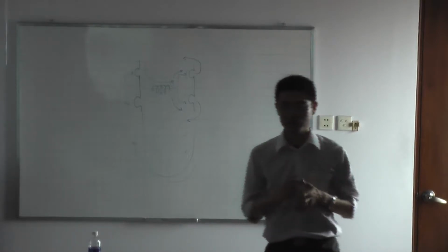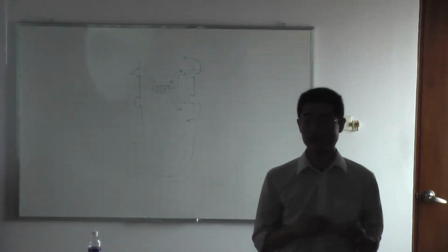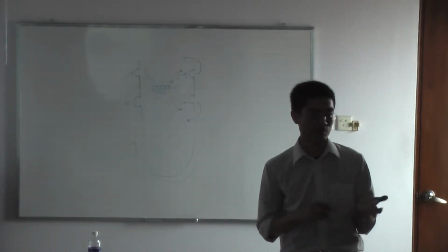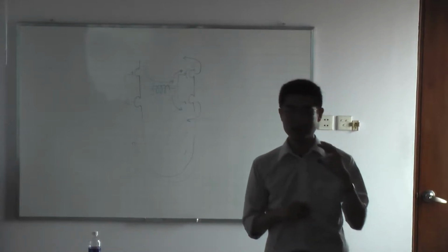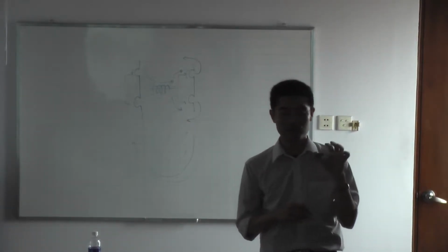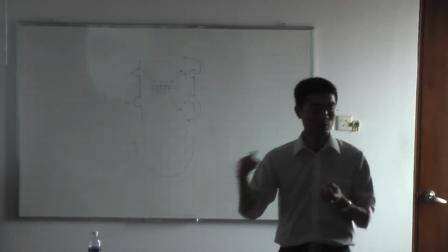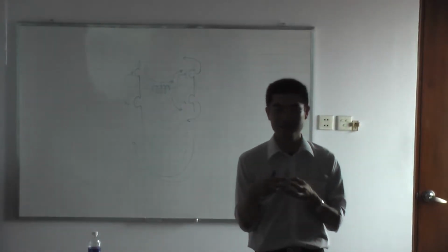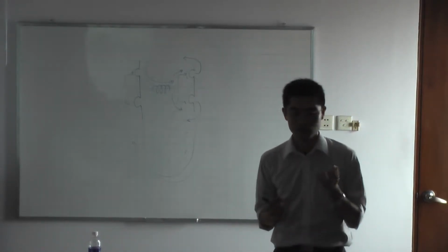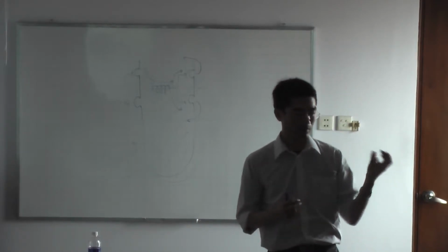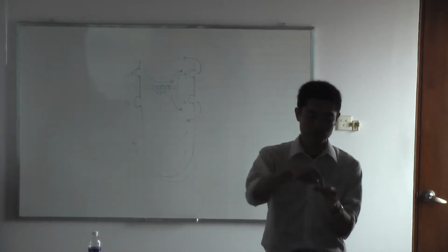And the next one is the prober. When we design, especially RF or very high-speed output circuits or high-speed input circuits, if we assemble the chip into a package, the package has a bonding wire and lead frame, and the bonding wire and lead frame always come with inductance. So its performance will completely change. So we want to connect to the pad by a 50 ohm system impedance as close as possible.